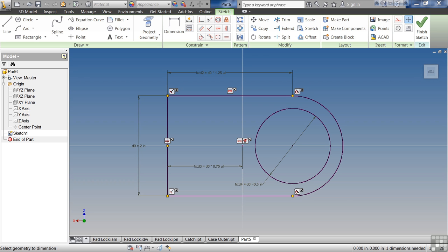In this sketch, you can see the simple formula used to calculate that the length is 1.25 times the width of this part. See that D2 equals D0, which is this dimension here, times 1.25. When you capture your design intent, you add intelligence to your design. The intelligence can exist in several different forms.